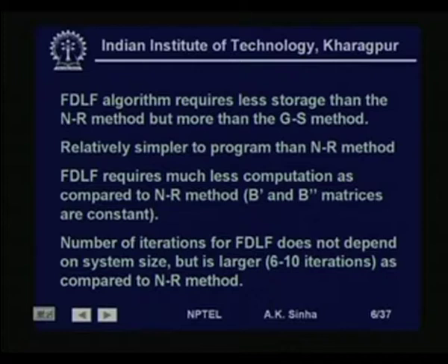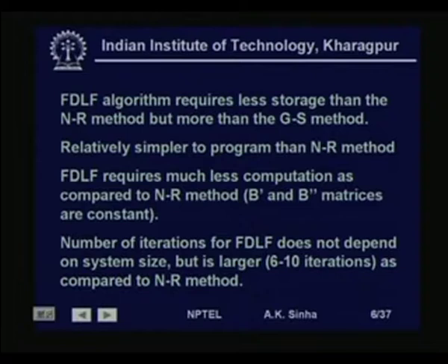The algorithm is simpler to program than the Newton-Raphson method. Again, this is mainly because the Jacobian element calculation is no longer involved here. The matrices B dash and B double dash are basically the susceptance elements of the Y bus matrix, and therefore, much simpler to compute.